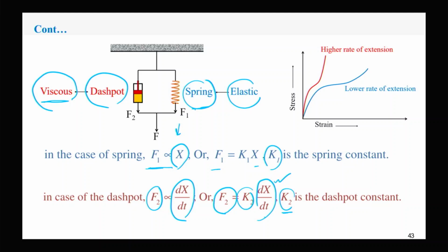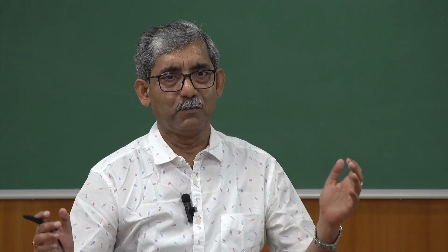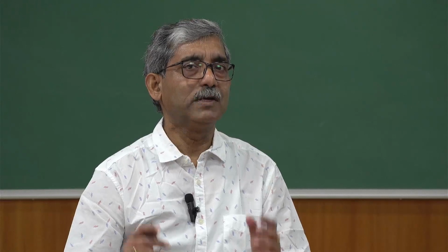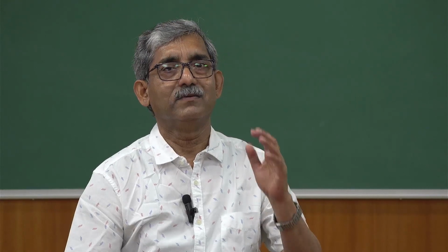Okay, that means it will resist more. But for 100% elastic material, springy material, which will be represented by a spring, with the rate of extension the strength will not change. But most of the materials available are viscoelastic in nature. That's why with the increase in rate of extension, the force required will be more.